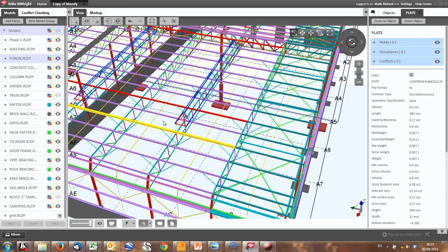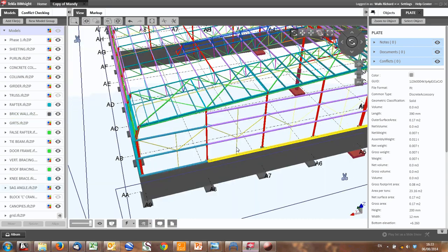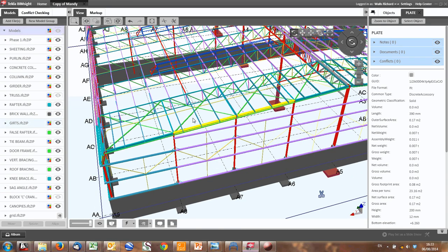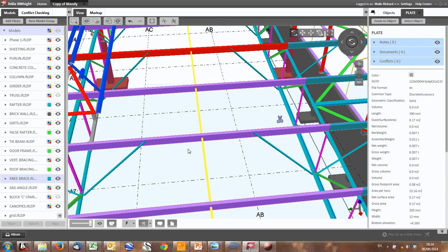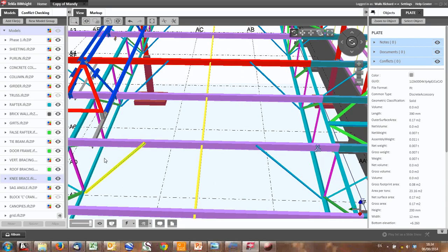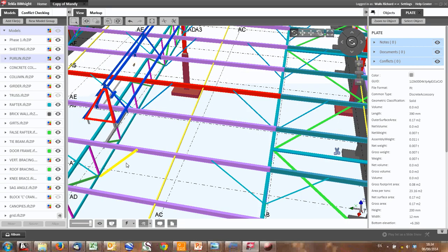It really depends on how they're erecting it, especially the girts. You can put one girt covering 2 bays. It just makes the work quicker. Right, so we can analyze this though as a simply supported beam spanning from truss to truss. These can be designed to support these, the knee braces. The knee braces stabilize the truss, but we'll look at those later.